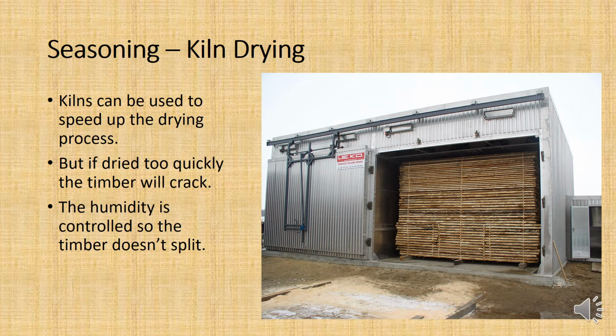Now, these kilns will actually raise the temperature, and because the temperature is higher, they will dry out the wood faster. So rather than having to leave the timber in an open shed for 2.5 years, you can put it in a kiln drying station like this, and the wood will be ready within a few days.